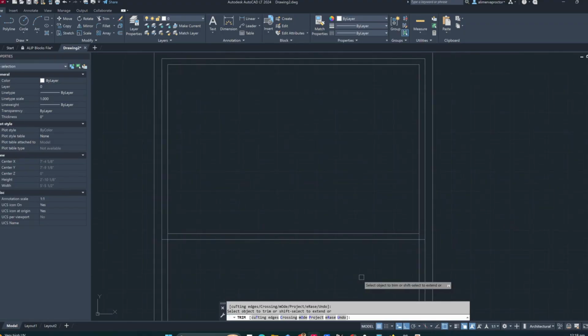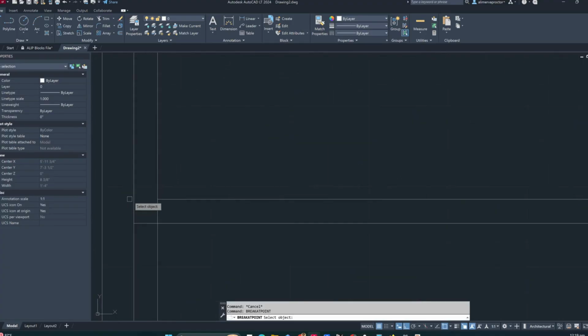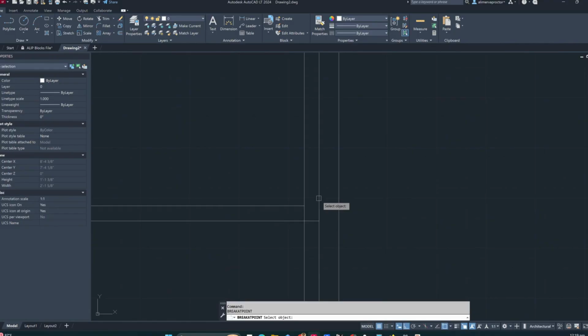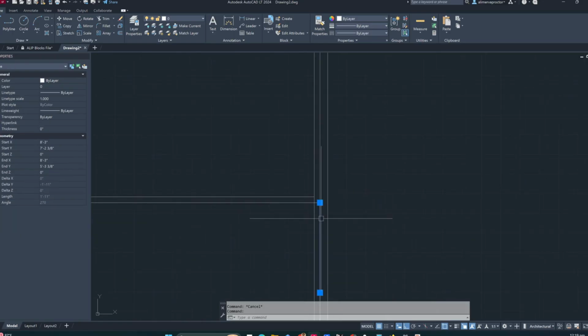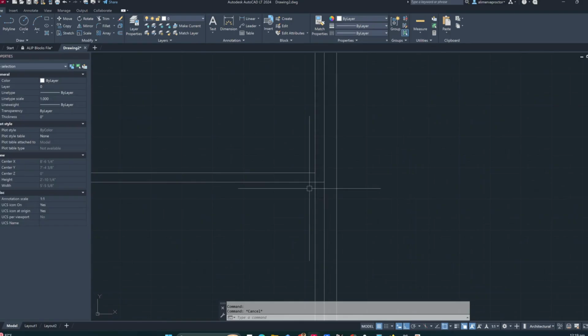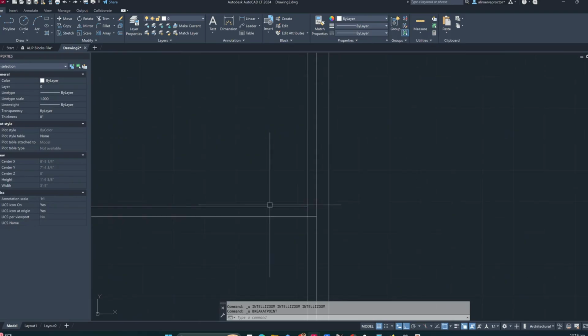Okay, and new command time, break at point. We're typing it, break at point. We touch it, then we're gonna go to this line, and then just touch that like that, and then we're gonna do enter, touch this, and go down to this piece right here, and it's now broken at that point, right? That's a nice cool command that you can learn, right?